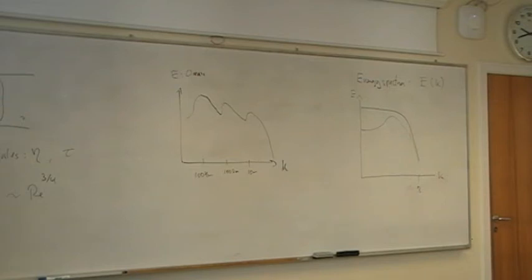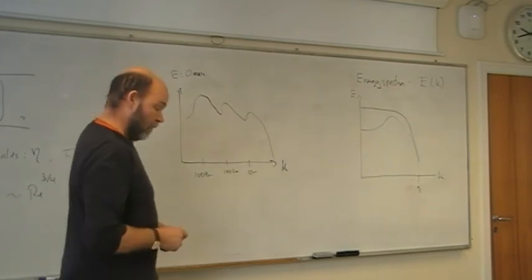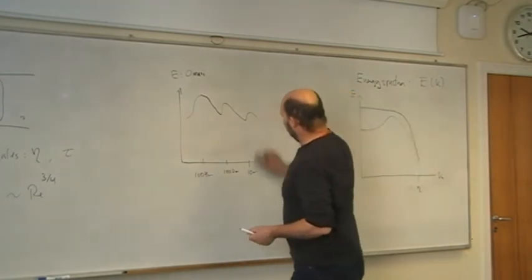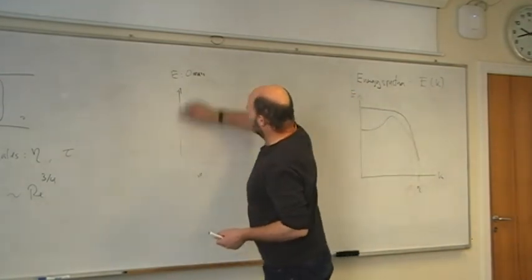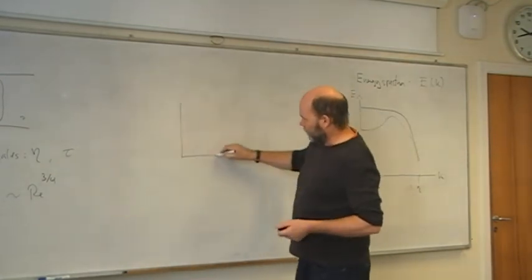You have to get very close to the wall. Kolmogorov will be around y plus of 1. Little smaller maybe. The distance you should have is y plus of 0.1 close to the wall. You really have to resolve that boundary layer. If you remember the law of the wall, it looks something like this.